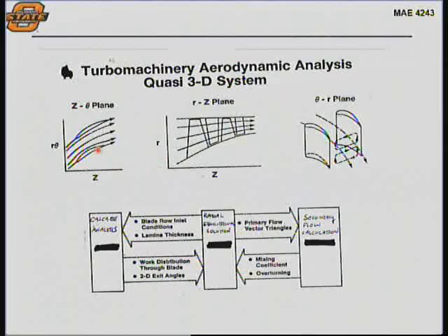And so you iterate this until all the flow stream surfaces converge, and you have a converged solution of flow through this turbomachinery. And you can add things to it, like that loss model, being able to predict what these secondary flows are. There are models that go into this. And so this is a two-dimensional calculation, this is a two-dimensional, and this is a two-dimensional.